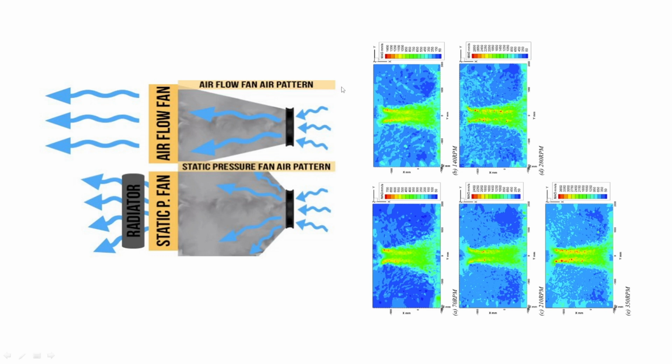Now, a little bit of science here. So we got the case fan. Let's pretend we have a heatsink right here over your CPU socket. The fan works by accelerating air through it, and to accelerate the air, it has to pull a small vacuum in front of it. So naturally the air starts drawing in towards the fan. Well, if you have a high quality fan or fans in front of it to supply this fan with air, it now operates much more efficiently, because instead of having to pull air into it, air is being force fed into the fan, allowing overall cooler CPU temperatures.